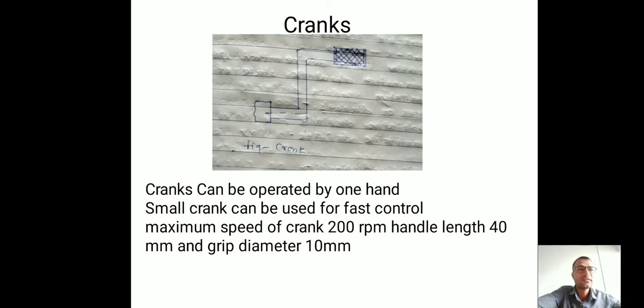So friends, always keep in mind while designing the crank, as per ergonomic specs, as per ease of handling, the length of this crank should be 40 mm and the grip diameter should be 10 mm, so that we can operate this crank at 200 rpm. Clear?